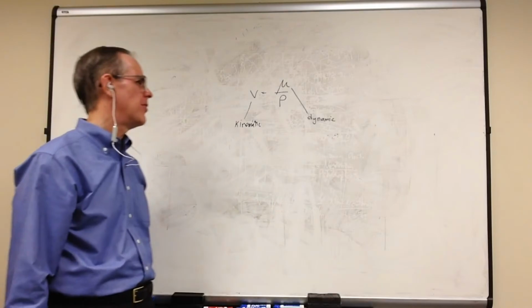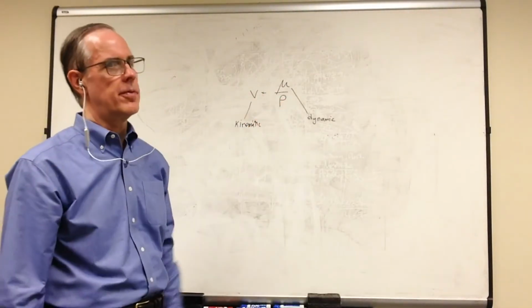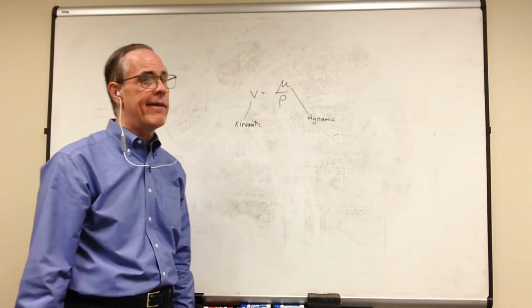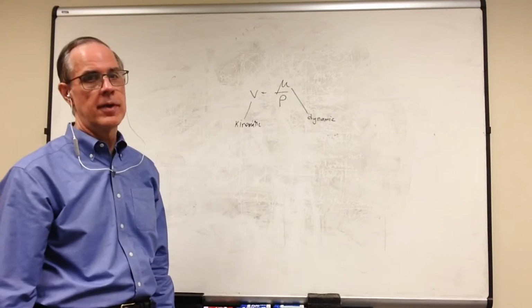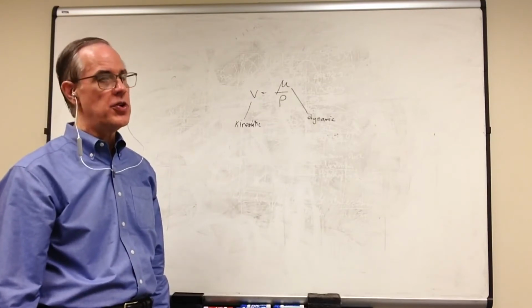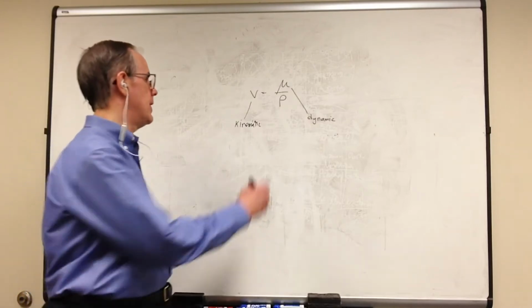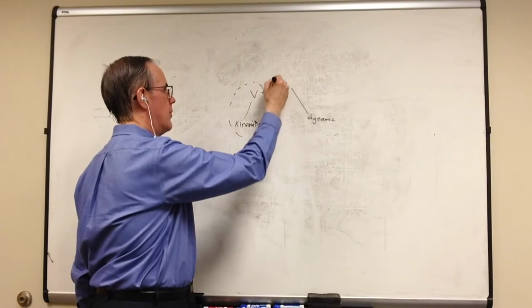Now, for an incompressible fluid where density does very little, if any, varying, this relationship is pretty simple. If you get something like air, things get a little more complicated because you've got different variations in density. As a general rule, if that's not an issue, it's much easier to use nu moving forward than mu. Why?